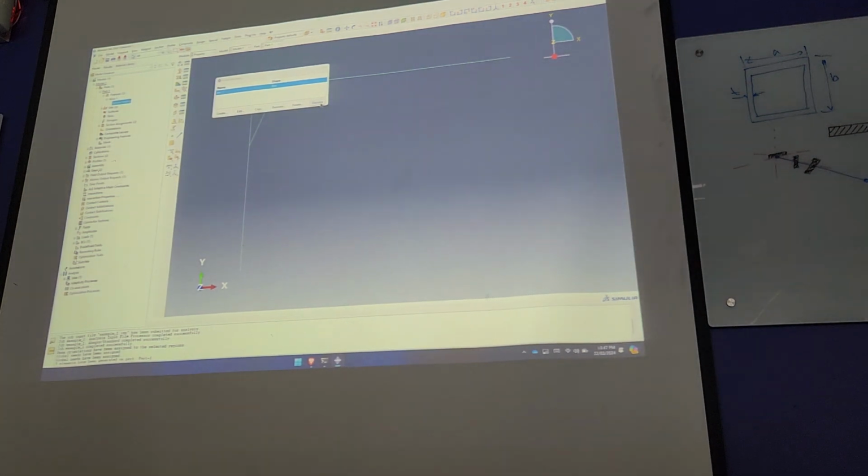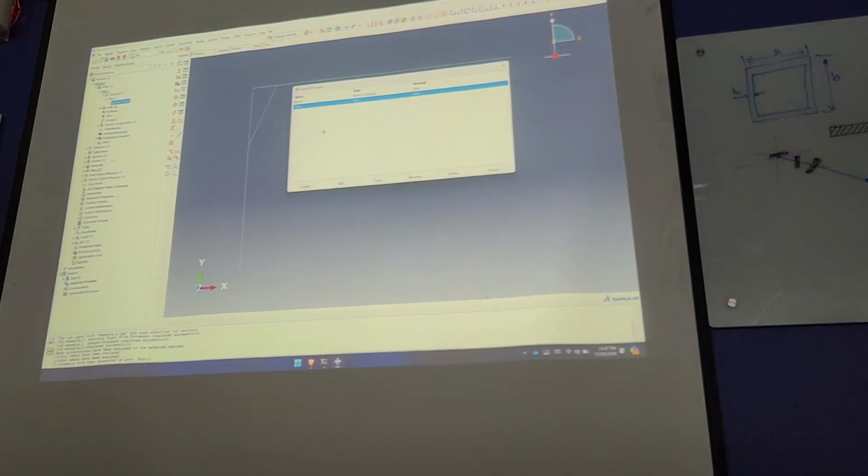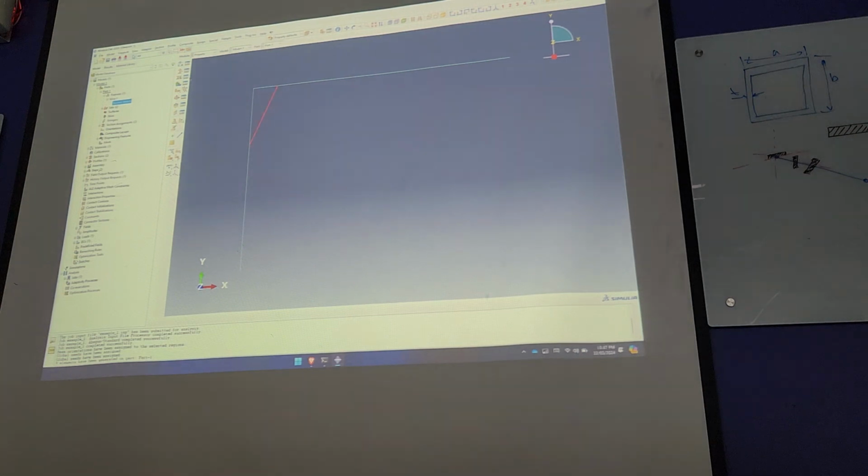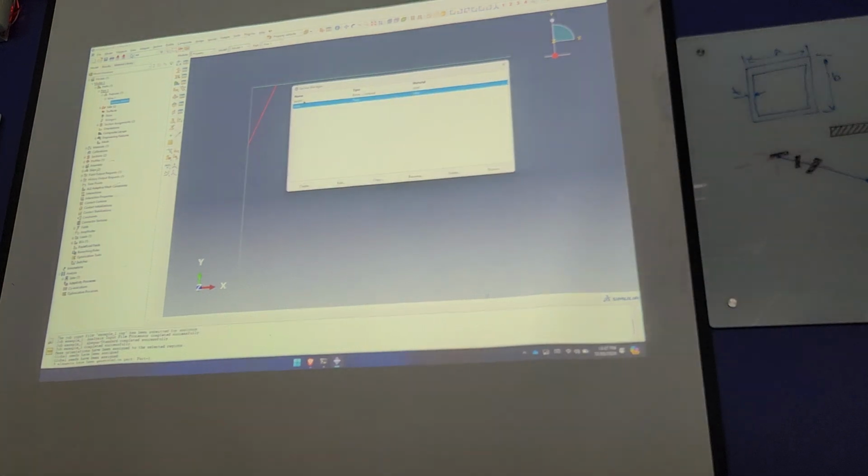What else do I need to change? Because my profile has changed, the length of the beam needs to also change, yeah? But we can also increase the actual truss cross-sectional area as well. So we can maybe go with more cross-sectional area, let's say 300.